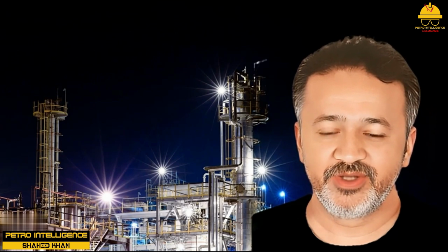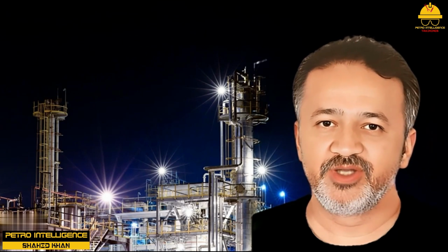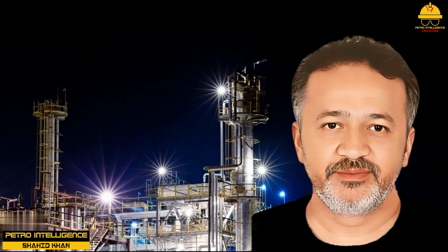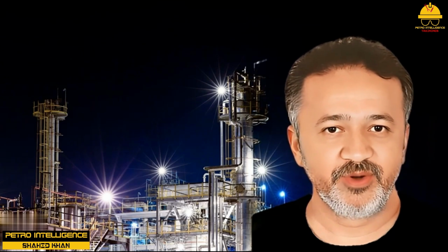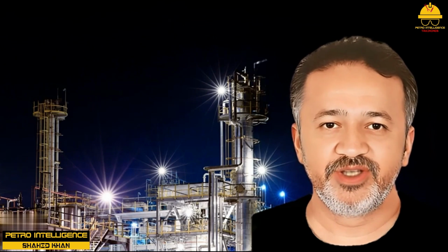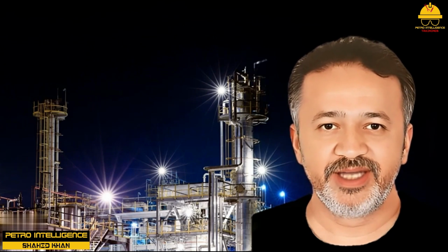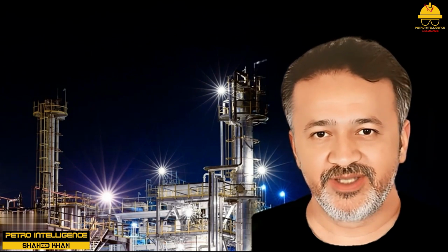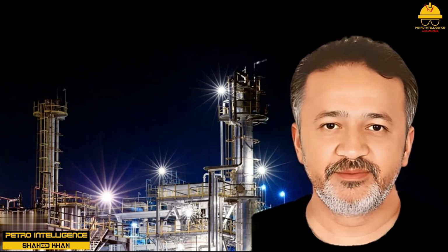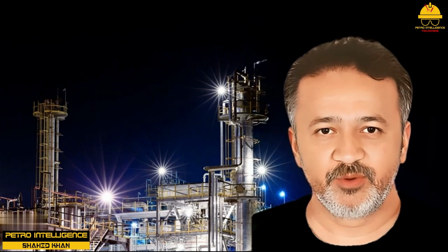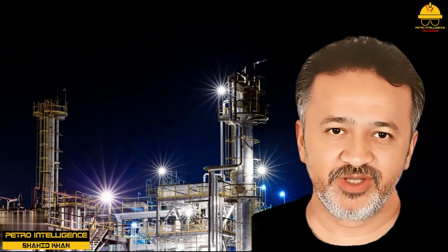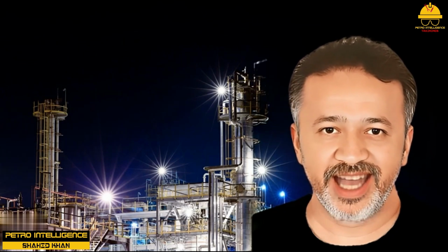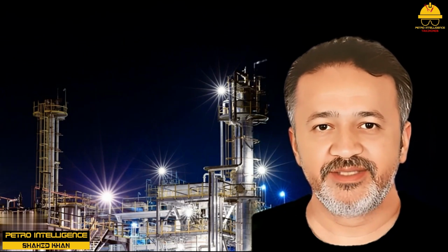Continuous and batch reactors. Industrial manufacturers use 2 basic methods of reactor operation, batch and continuous. In a batch operation, raw materials are weighed carefully and added to a reactor. The raw materials are mixed and allowed to react. After a predetermined amount of time, the batch is dumped, and a new batch is mixed. Continuous reactor operation adds raw materials incrementally to the reactor. Finished products flow out while raw materials flow in and are exposed to catalysts, pressure, liquids, or heat.